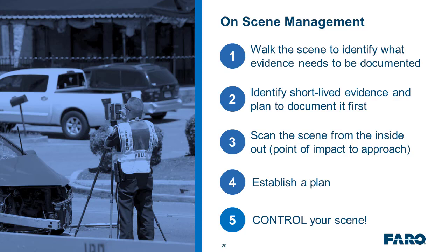The thing I want to mention, if you do not have the most current version of the firmware upgrade on your laser scanner, is that there are some new features, namely the photo retake option, and now the scanning pause option. So if you can see something coming toward your scanner, you can pause the scan and then continue when that object goes through. So it's a great new feature that was just released a week or so ago.